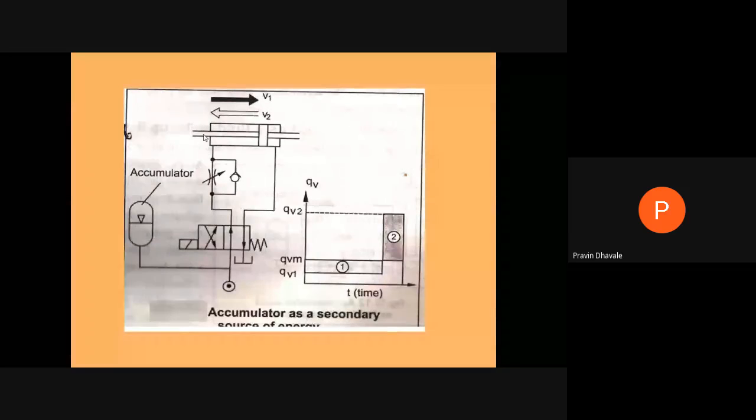Whenever a fast movement of the piston from right to left is desired, for that short period of time the surplus supply of high pressurized fluid from the actuator will be used by using this second position, so that the pump is able to supply a limited pressure of fluid to move the piston from left to right.